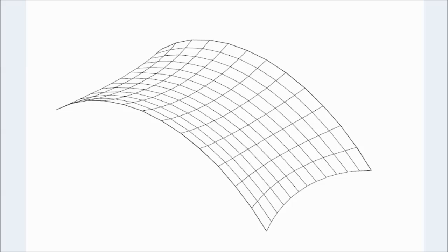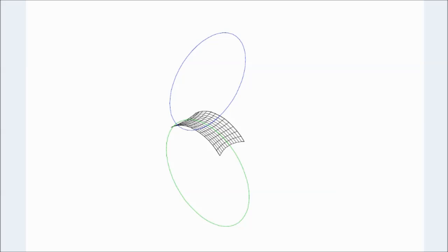As our model for this discussion, we'll use a simple 120-inch by 240-inch barrel vault roof between two arch supports with cables on the bottom edges. A tensile structure's shape is maintained by the balance of two hoop stresses along the principal directions of curvature. These are shown in blue and green in the drawing. The hoop stresses are the result of pre-stressing the structure by means of compensation and also of the structure's specific shape, which determines the size of the two hoop radii.